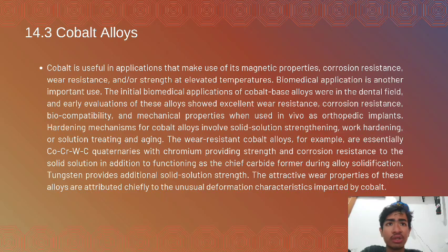In the wear-resistant cobalt alloys, for example the essentially Co-Cr-W-C alloys, chromium provides strength and corrosion resistance to the solid solution in addition to functioning as the chief carbide former during alloy solidification, and tungsten provides additional solid solution strengthening.